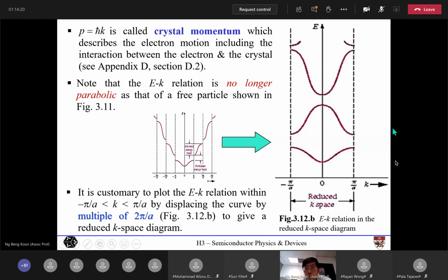which describes the energy against the momentum of the electron in a crystal. Qualitatively, you can think of this as the kinetic energy of the electron versus the velocity of the electrons in the semiconductor. That's similar. As I mentioned before, the part downwards is the energy states filled up with electrons in the crystal, and the part above is the empty states. This refers to the conduction band, the EC part, and the part downwards is the EV part. Of course, the separation here is the band gap.